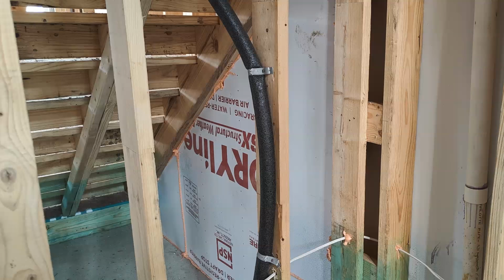Missing one or the other creates a misalignment of the air barrier and thermal boundary, which together make up the thermal envelope of the building. That's why code specifies that these must be continuous and always aligned. So if they ever are out of alignment, that's a misalignment of the thermal envelope, either on the air barrier or thermal boundary side, which both make up the thermal envelope. So hopefully that explains it better.